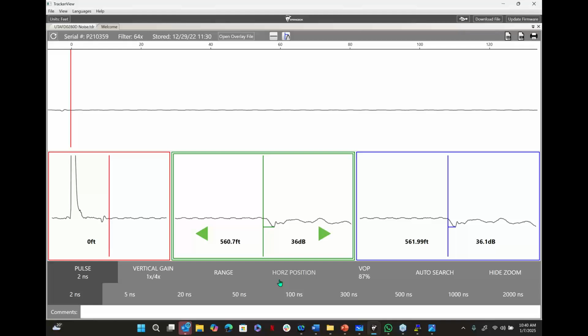In cable TV, we rarely go above 3,000 feet because of the amplifier spacing. But some of our TDRs, by ours I mean all of us in the TDR industry, are made for the most extreme cases, like Australian Telecom. We have TDRs that quite literally can see out 4 or 5 miles. So when you see some of these TDRs that have distance ranges of 15, 20,000 feet, that's not a myth. They really can go out that far.